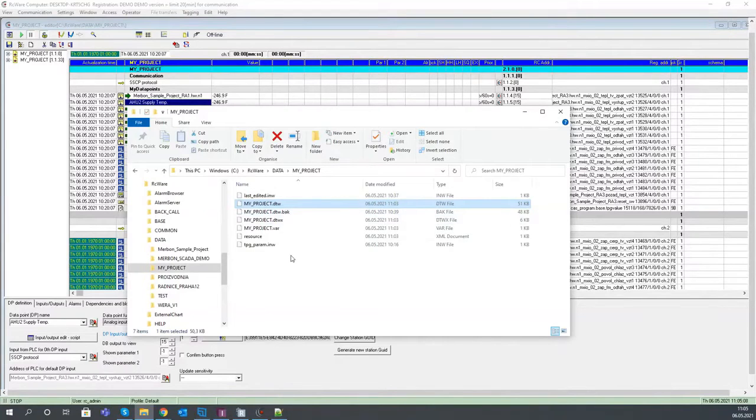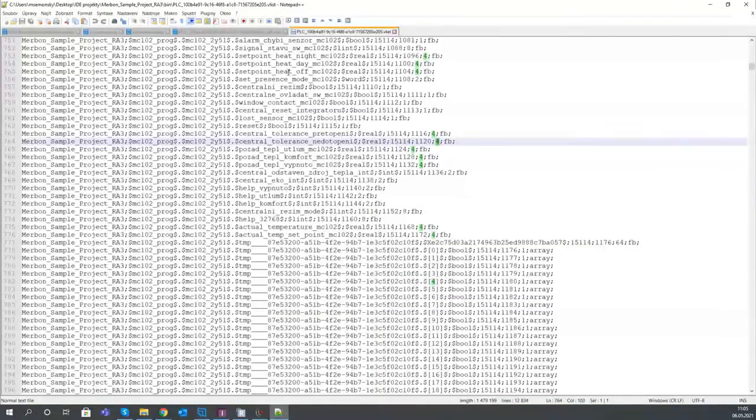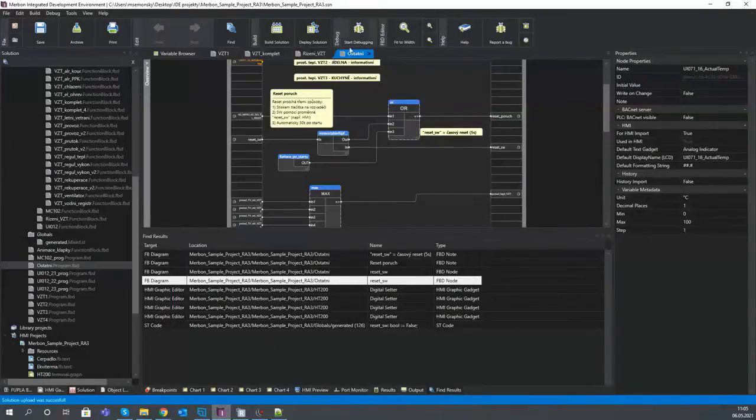The other question is, if you engineer the PLC, make changes, etc., does the structure of the memory change? Well, it may change, and this is actually why we use these COM IDs. Because if we engineer the PLC, every inserting of a new variable or of a new function block or whatever fills the memory with data or with the position where the data will be stored. And the memory, of course, has some structure.